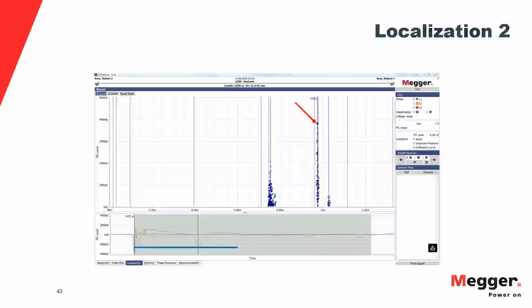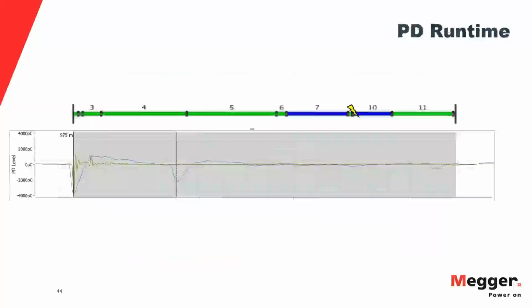What you might notice here is that our initial pulse and our reflected pulse look similar, but my reflected pulse is considerably shorter and a little bit wider than my initial pulse. We call that effect cable attenuation and dispersion. Attenuation increases as the cable length increases, as the pulse loses energy to losses in the cable system. It basically lowers the magnitude of the signal. And what happens is a marginal signal can then become unmeasurable.